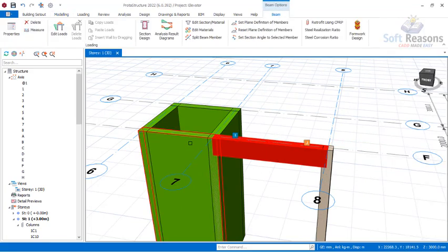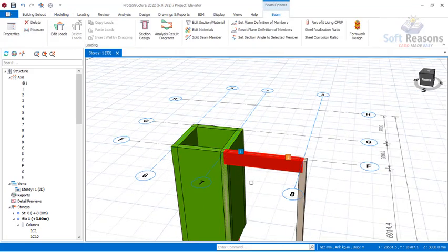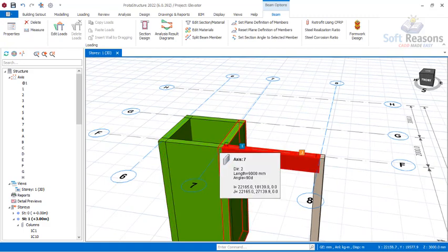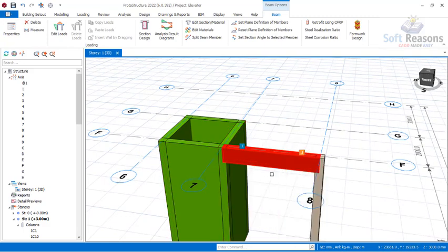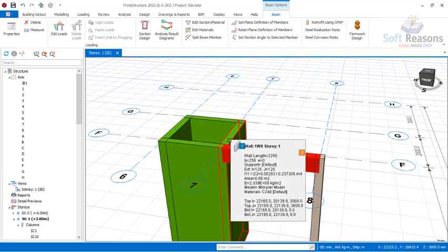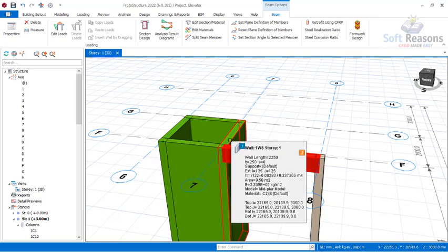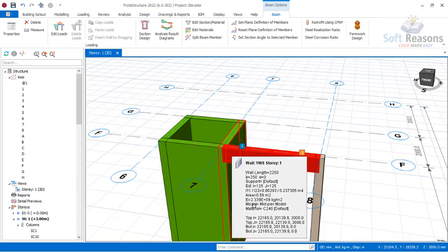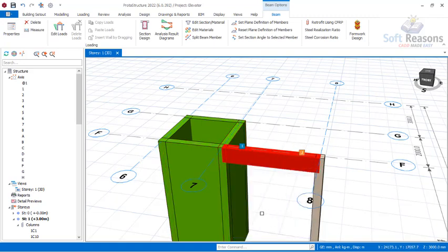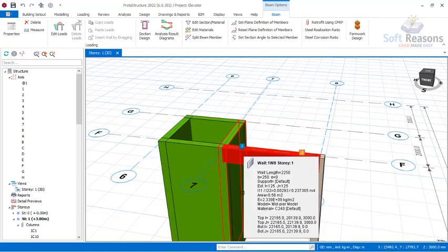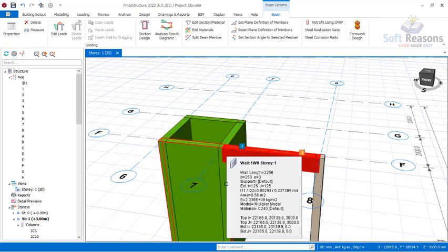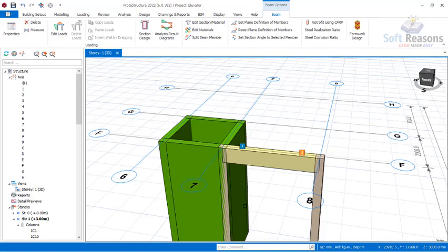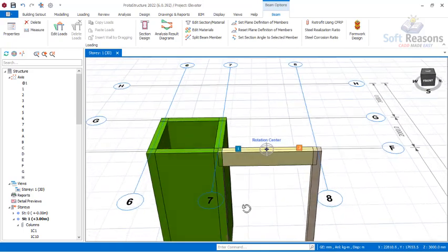So at every point of connection of your reinforced concrete beam to a wall, there should be a column to carry the beam and not the wall itself, because if you are connecting it to the wall directly, after your analysis and result, you know that the wall is dead. The wall will be dead, not even failed, it will be dead. You will struggle to make it past analysis, most especially when you are designing a high-rise structure. I've experienced that. I'm talking out of experience and not out of statistics.